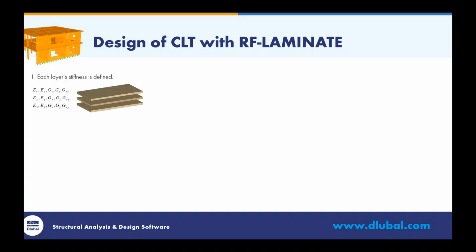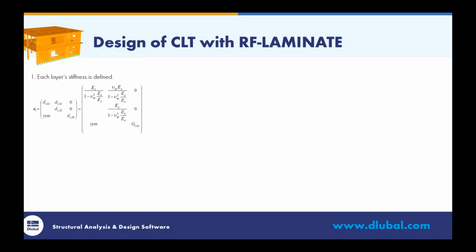Pretty soon we will go ahead and define the individual layers for our CLT compositions. And each individual layer has its own stiffness matrix based on the modulus of elasticity and the shear modulus. And we can see a simple example of a single layer stiffness matrix here.